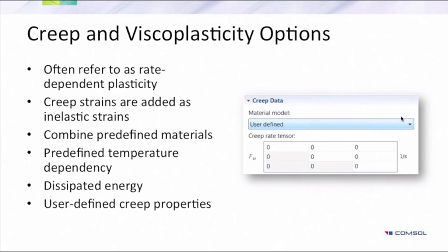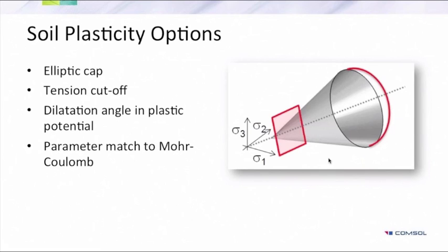So in creep you can combine different creep effects with each other, and you can also prescribe your own creep rate tensor. And again, as you see here, since you can type a number, you can also type a relation, so that you can have creep depending on stresses or some other variables that can be calculated in COMSOL Multiphysics.